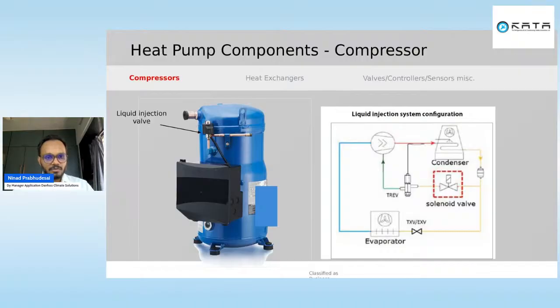So certainly the first one is the compressor. In compressor technology, there are of course screw, scroll, and semi-hermetic reciprocating compressors which are already being used. Now, as I said, there is a requirement of up to 150 degrees of heating in the process. In that case, the existing components cannot be used as they are because they were not qualified for that. But now slowly organizations like Danfoss are coming up with new series of compressors and other line controls.